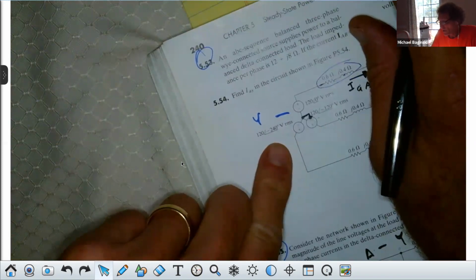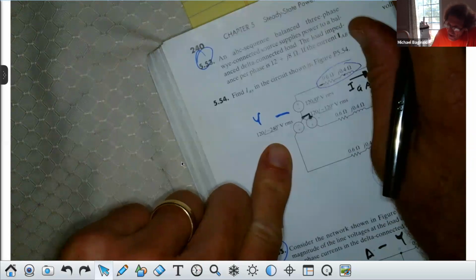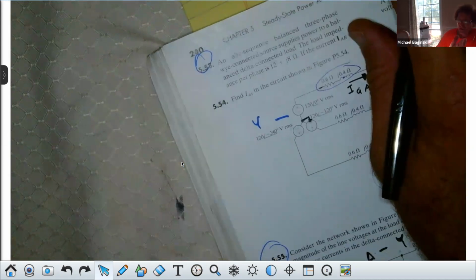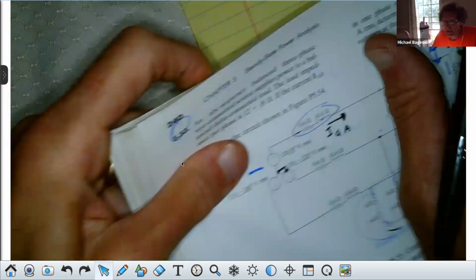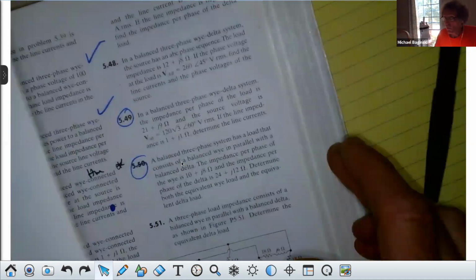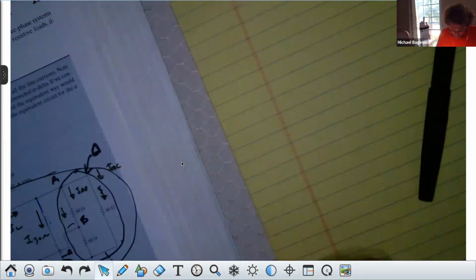Now, the logical question is, why would they do that? And the reason is this in a nutshell. Because now the average power delivered to the load, assuming all the loads are the same and all three phases, all the power delivered to the loads is a constant, and the peak power is equal to the average power. Got that? That's the reason they use three-phase power and not single phase, because then you get something where there's a peak power, then it goes to zero. Peak power, zero. That causes a lot of wear and tear on, well, theoretically on the lines. It causes what's called transitory behavior.